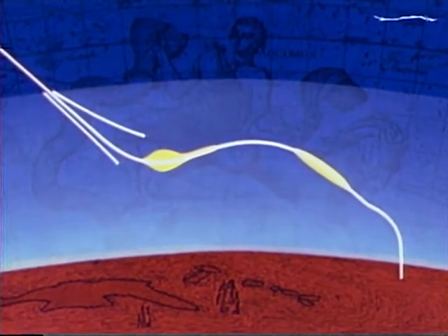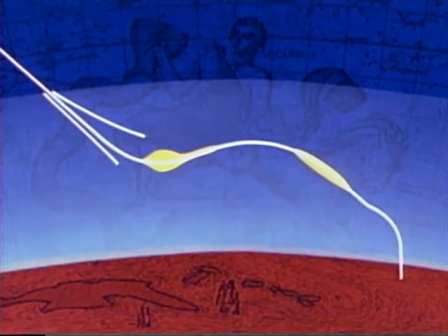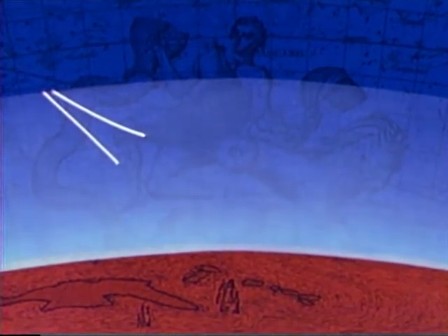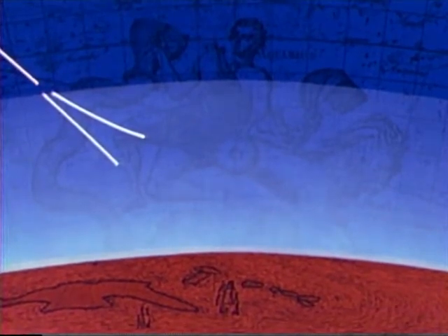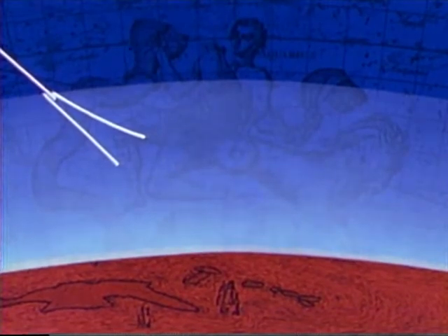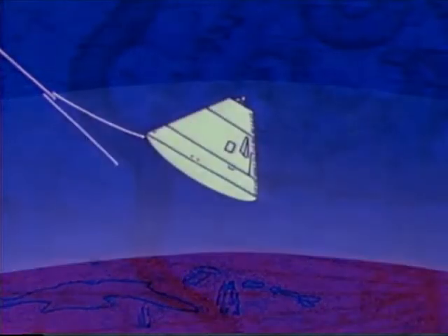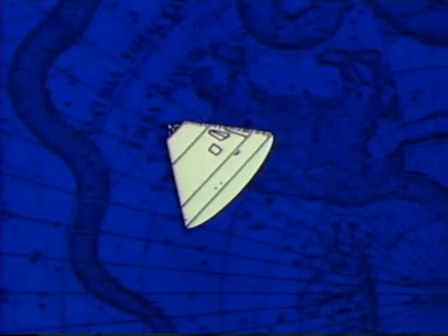We will now examine the entry trajectory in detail and see what occurs during each portion. As the command module enters the fringe of the atmosphere at 400,000 feet, there will be as yet no aerodynamic control. Before this point is reached, the command module will be aligned to its stable trim attitude. It should be noted that there are two stable trim attitudes. The desired one is blunt end forward. The other is with the small end forward. Since the heat shield is on the blunt end, this entry alignment would be disastrous.